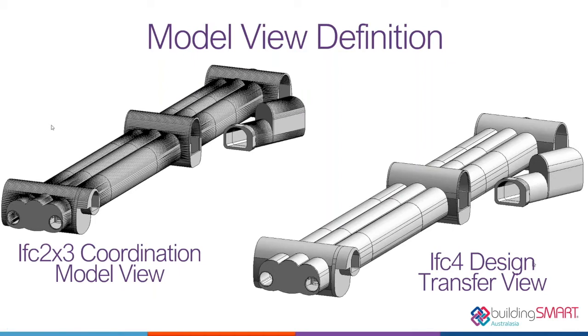export. For several reasons, and I won't go into a lot of the detail of this unless there's questions raised on this, the most reliable version of IFC to use at this particular point in time is still IFC 2x3. And the main reason for that is that the software that you're commonly using is certified probably only against the version of IFC 2x3. So buildingSMART do test and audit and try and verify implementations of IFC to say that they're compliant and producing valid files.